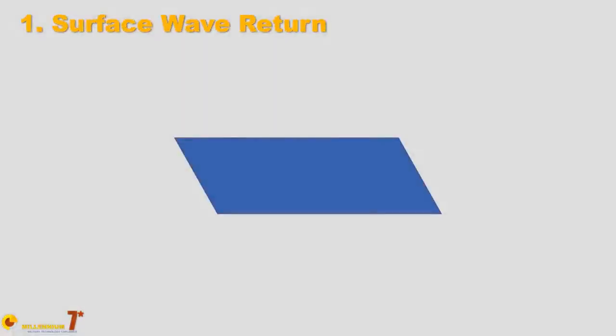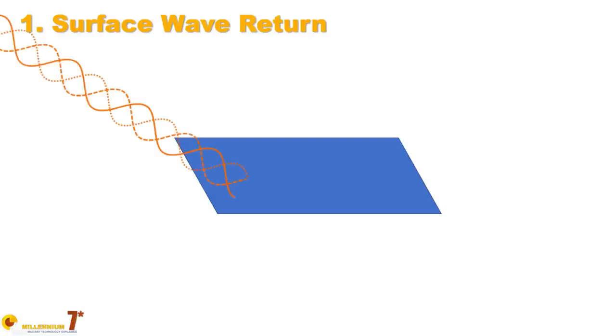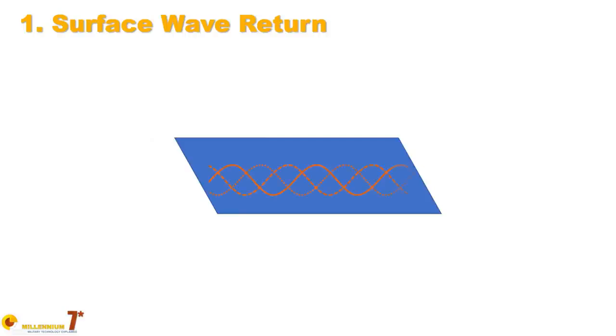The surface wave happens on a conductive component, like an antenna rod or a metal plate, when it is excited by the impinging radar radiation. The element behaves like a transmission line till a discontinuity is encountered or the wave gets to the edge of the component.